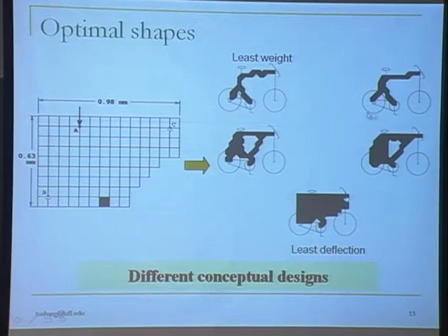So we can see here, from here my evolution takes me to this location, from here to here. That is, I have an added stiffener over here, which will reduce the deflection, though it has a cost of increasing the weight. Then I also see that this rear section becomes heavier, so that further reduces deflection, but as we can see that weight has increased, and so on.